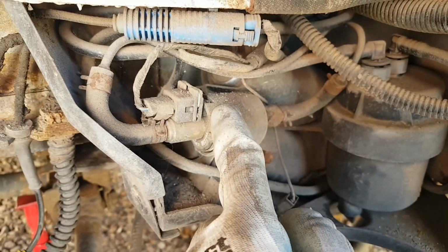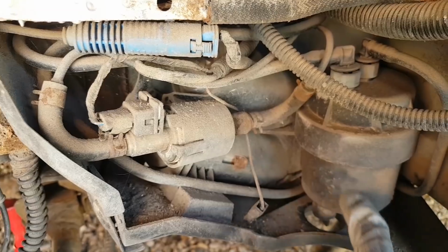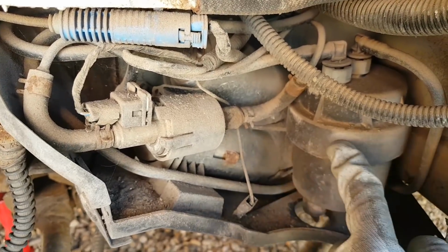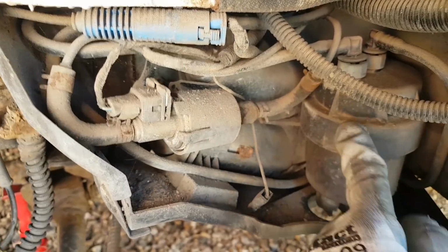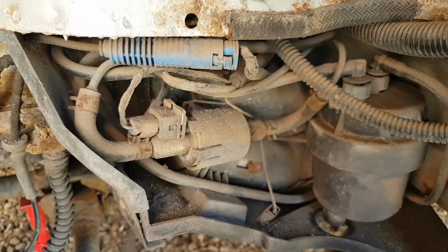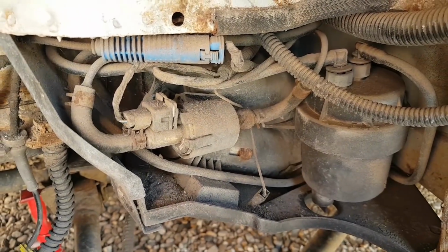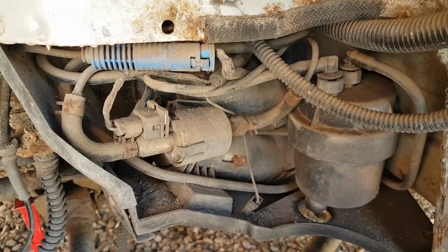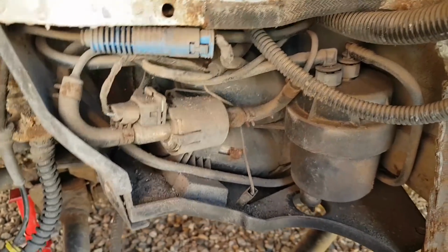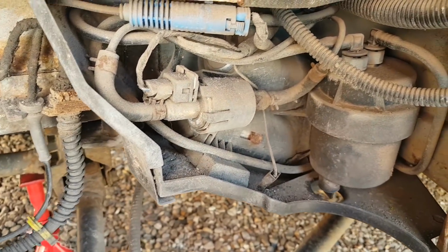And I think I'm just gonna take the whole assembly out, change the fuel filter. That's a must now, we're gonna have to change it, and then have a look at the pump. I'll take the filter first, see how it looks. It may be that the filter tells us what the problem is. If the filter is too dirty or something like that, then we'll know maybe it was just a filter problem. Okay, let's try to take this off. It's all rusted, it's been a nightmare to get to this.